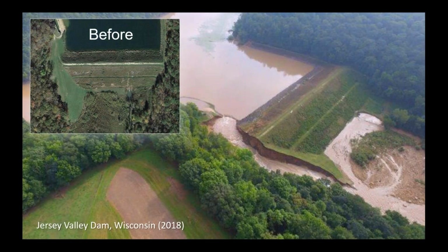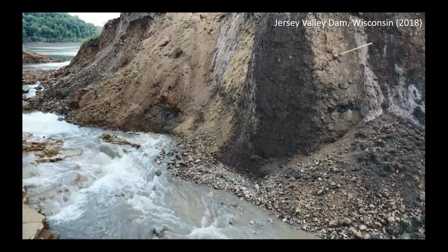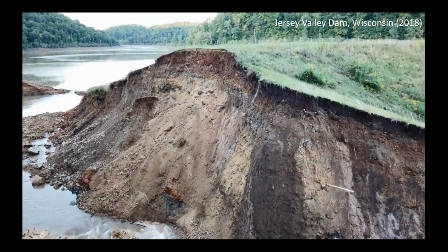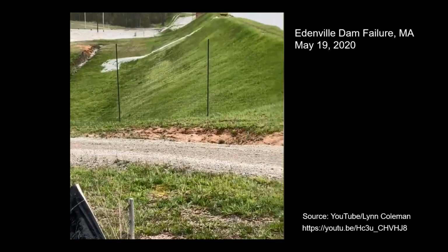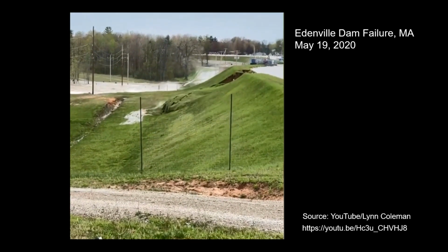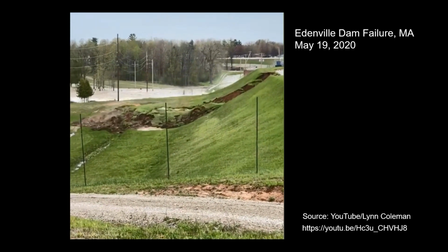And then very recently, here we have Jersey Valley Dam in Wisconsin in 2018. This is a pretty classic looking NRCS type dam. You see the before. And in this case, the failure of the embankment didn't occur. It was a failure of the earth cut grass line spillway that resulted in a complete breach of the dam at the right abutment of this dam. And then the most recent one here, Evansville Dam in Massachusetts, just a few weeks ago, May 19th, 2020. And we caught this dramatic video of this dam failing.